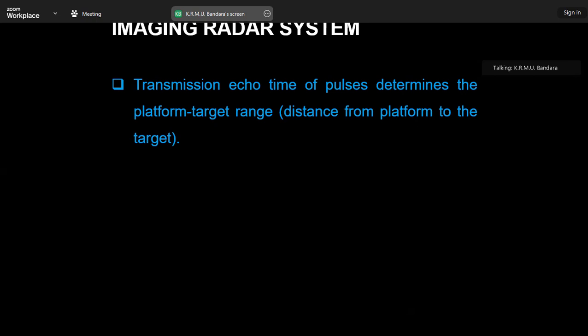It's not the same, because the GPS clock is an atomic clock, very accurate and precise. But the receiver we are using, even a high accuracy receiver, has a good clock but there is some time difference. That is why 4 satellites are necessary to find the 3-dimension coordinates, because for the 3-dimension receiver position XYZ, we have to find out the time difference too.